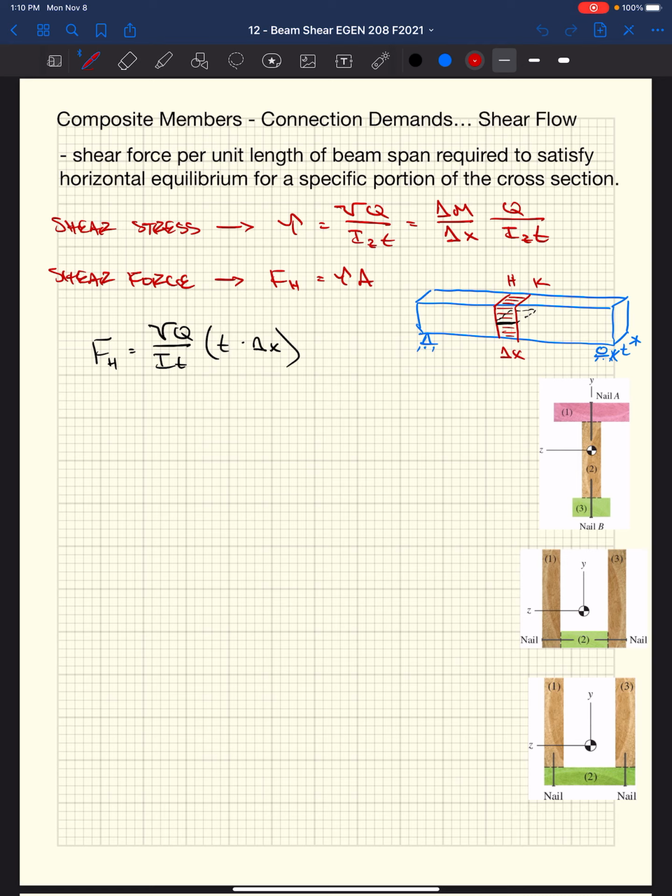But before we step away from shear and beams, we talked about, or started talking about, this idea of shear flow on Friday, which is the concept of creating a composite section out of multiple other sections, other materials or different dimensions of the same material. I mentioned I-joists in wood construction.